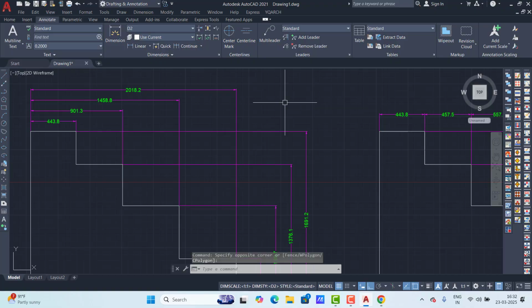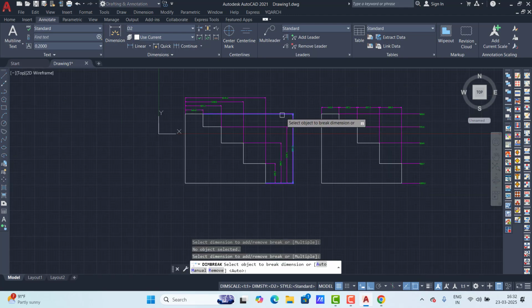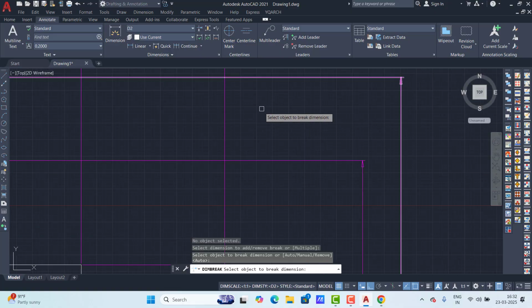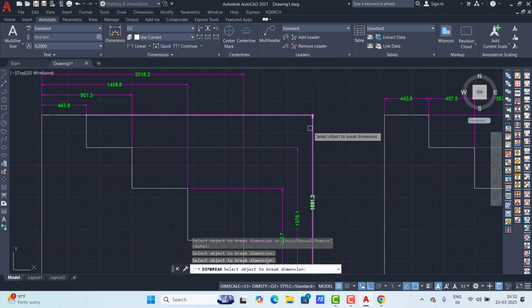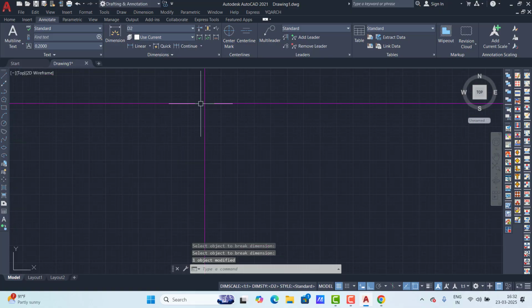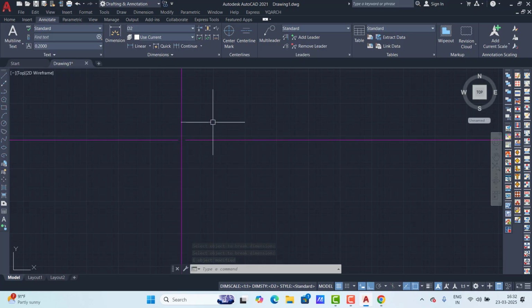Now leader structure. Leader structure means first I click on the object, second I click outside, and after that I click again, and that time the text comes. That is leader structure completed in 3 steps. If I click the object and click outside, that means the text comes in 2 steps. So you can use more structure formats. Now here are the first segment angle and second segment angle.